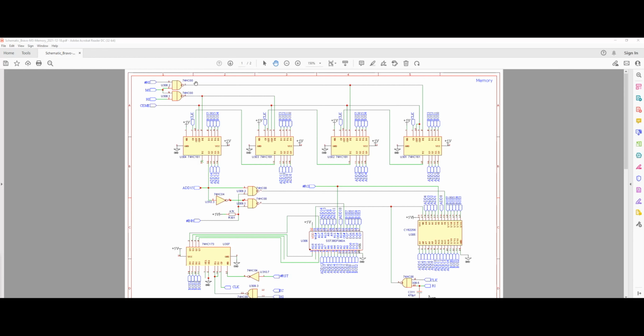And that's what we need to read the data from the bus into our register, because the parallel enable signal on these chips is active low. So in order to read the data from the bus into these chips, we need to bring pin number 9 low, and that's what is happening here. Once we have done that and read the first 8 bits into the low byte side of our register, we bring the HI signal high, which causes the inverted HI to go low.